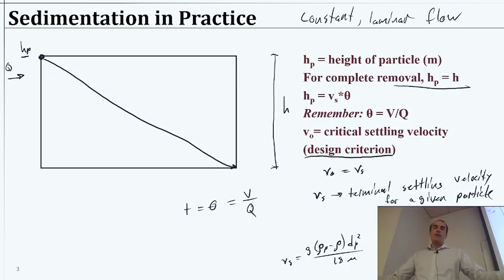But, okay, if we have some space and we have to treat some flow rate, then how good can we do before we need to just say, all right, let's keep it a little smaller, then let's treat with coagulation and have a second clarifier or second sedimentation basin. So it is a very good question. Usually about the size of silt particles, so tens of micrometers, are about the smallest we could do. And even those, usually we might expect to not get all of them, so maybe 20 to 50 micrometer particles would be typical.